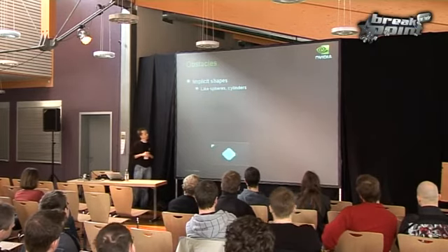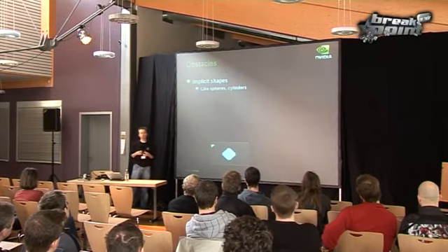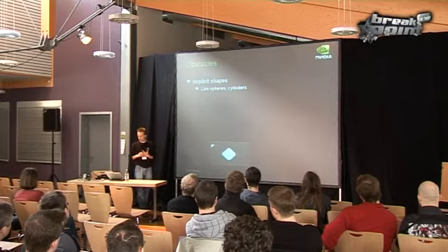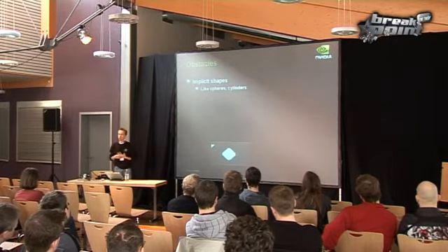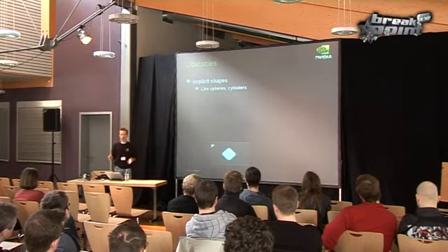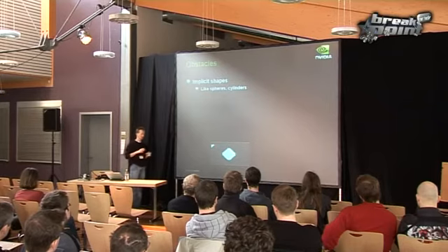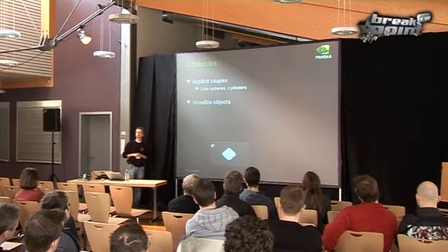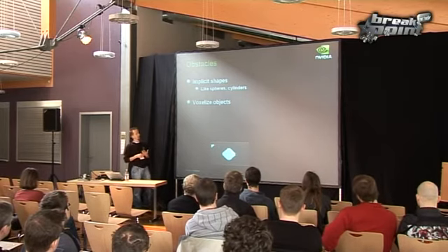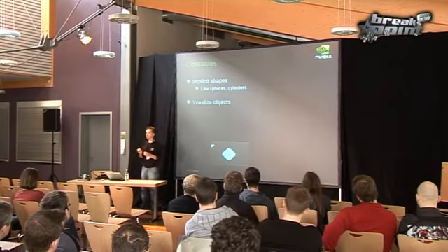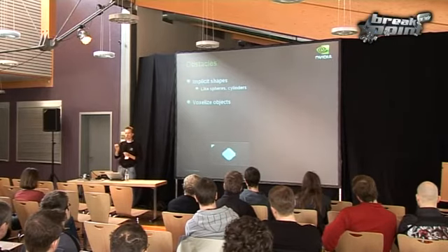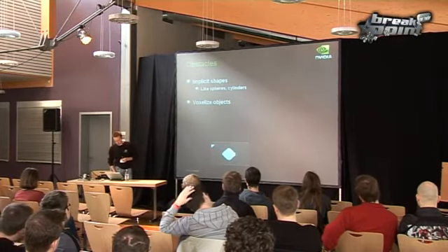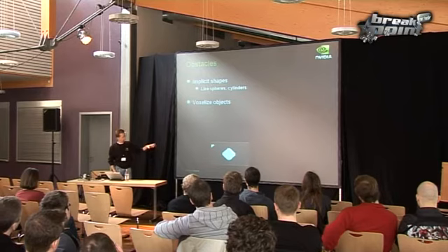So how are we going to do that? First off, we need to find a way to represent our solid geometry, to somehow communicate this information to our simulation. One approach is to use implicit shapes. We can define some shapes procedurally, such as spheres or cylinders, to approximate the overall shape of our solid geometry. Or we can actually voxelize objects, which means we can take our triangular mesh, discretize it, and find out which cells are occupied, which cells are within the geometry, within the object, and which cells are outside. So we need to come up with some sampled representation of our geometry.